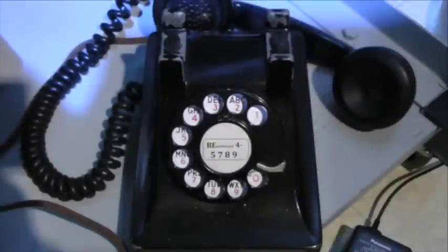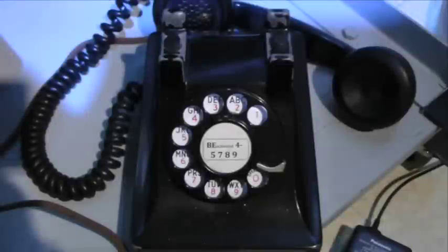Okay, so let's go back now to the connected stage once again, and we're just approaching the end of a telephone call, but this time the calling station remains off hook, and only the called station hangs up. In the connector, only the D relay releases because its loop through the called telephone set is open. So other than the D relay, the switch remains in its connected stage and is under control of the calling station. So now let's see what happens when the called station attempts to originate a new call. The call begins by lifting the handset out of the cradle.